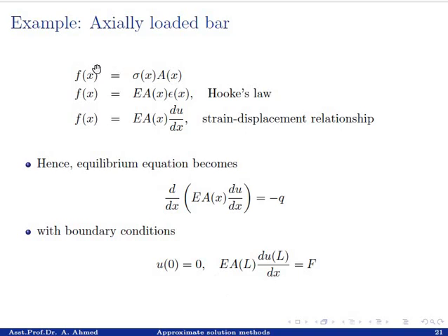where I know that the internal force f of x is nothing but the stress inside the member times the area over which it is acting. And from our definitions, the stress is the Young's modulus times the strain, and incorporating the definition of strain, which in this case is the strain in the x direction, it's simply du over dx. So now the internal force f of x equals E A of x times du over dx.